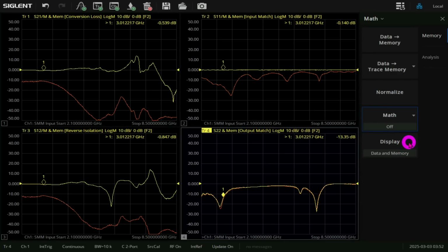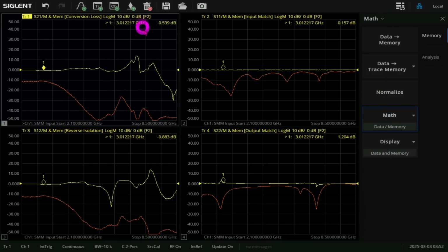And even here on this port, we expect the Q port to be very similar to the I port in terms of its return loss. There you go. So now if I look at this marker, this number I'm reading here is not the difference, which is the IQ balance. So you can see that the Q is a little bit different by about half a dB or so. Not a big deal. Even in reverse, they're very, very similar. So it meets its specification. And look how easy it is to manipulate the data and very quickly figure out the performance of the mixer.